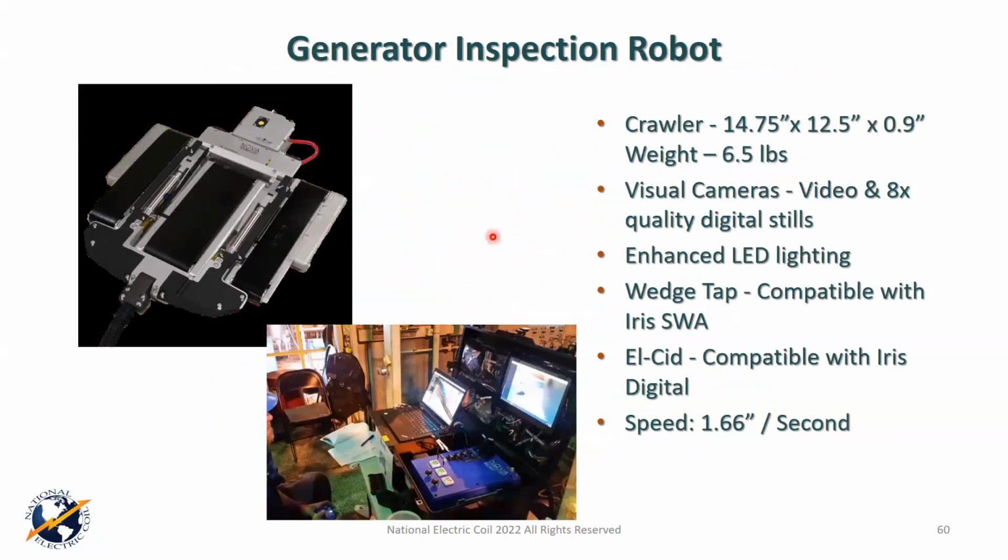I want to share a little bit about robotic inspection. I mentioned it earlier. This is becoming more common, and there are limitations, and I mentioned some of those, and I'll hit it again in a minute. But this is the actual robot, the trolley that goes inside. This is the umbilical cord that goes out. And this fits into the air gap, and it has tractors on this model that go up against the rotor, and go down against the stator, and you can actually drive this sucker.